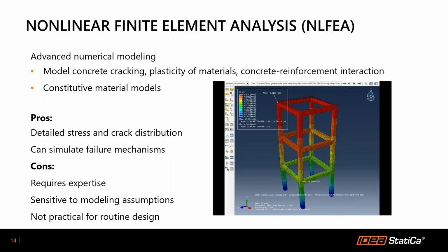About nonlinear finite element analysis, these are advanced numerical modeling. Now I'm talking about modeling in software such as Abaqus, ANSYS. In these software packages, you can model concrete cracking, plasticity of materials, concrete-reinforcement interaction, and you can input constitutive material models. The main advantage is that it allows you to capture in detail the stress and crack distribution, and it can